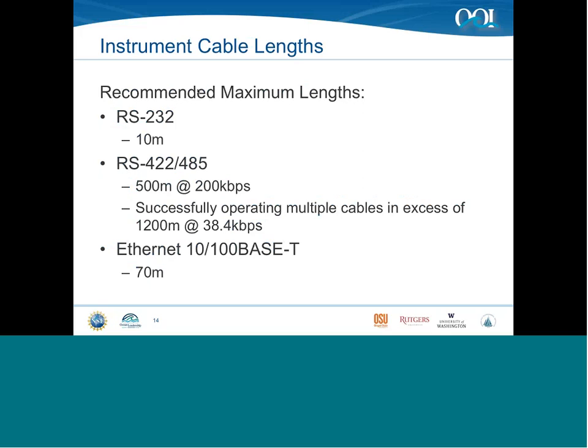And so again, back to cable lengths. The communication protocol and the cable lengths are kind of important. So if you, again, using the maps that Deb showed, how we have the site maps, so if you know that you need to be, let's say, 50 meters away from a junction box in order to be at the study site, you'd want to have some excess cable to make sure that you can get your instrument there. So you might want to plan for a 70, 100 meter cable.